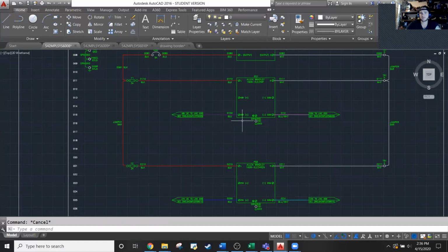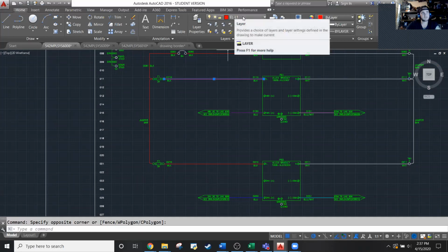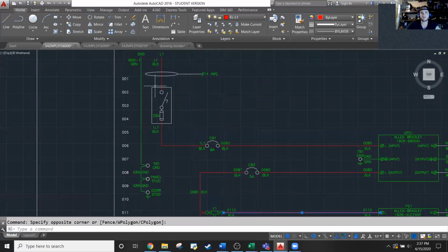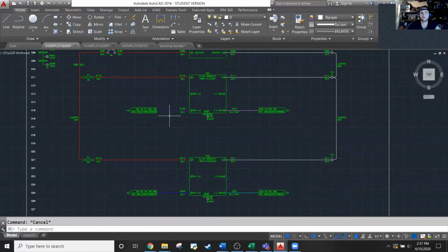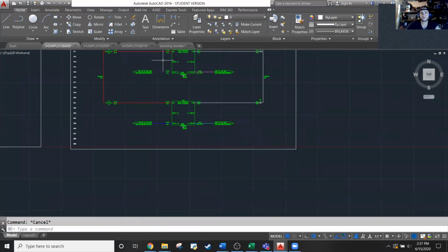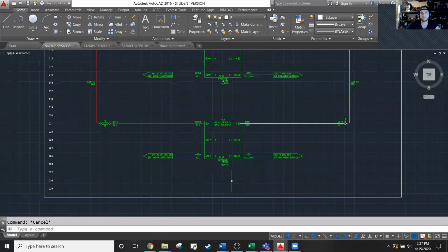You'll see here also the 120 AC was red and white. They're not calling it 120, but you're supposed to know that L1 is this incoming line 120 AC. And then the purple is 48 volts positive. Pink is 48 volts negative. And you'll see the same thing down here with your blue 24 volt positive, and teal is negative.